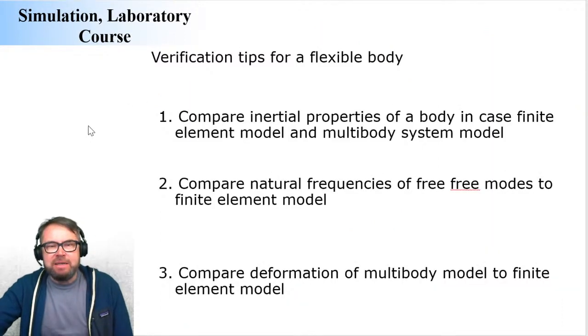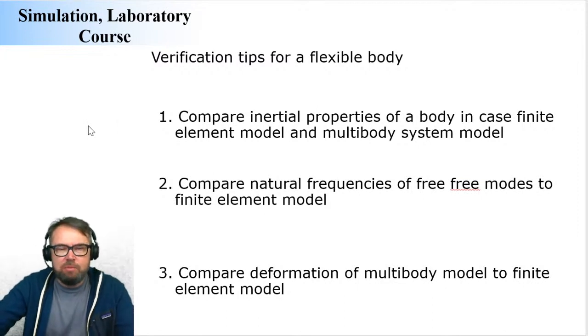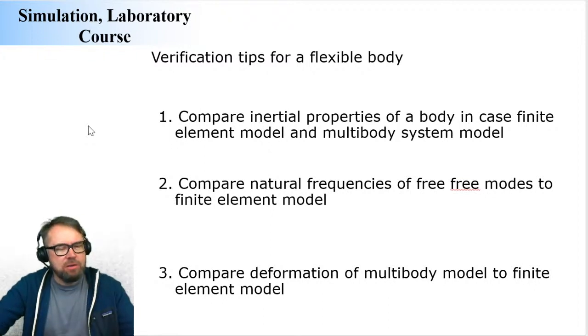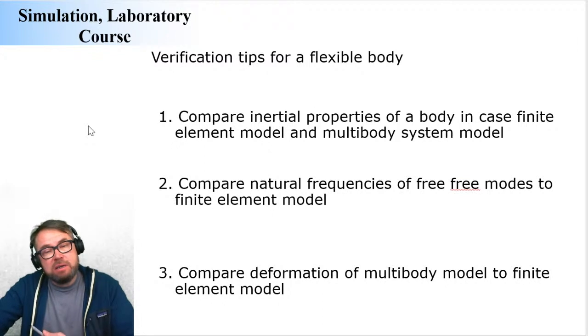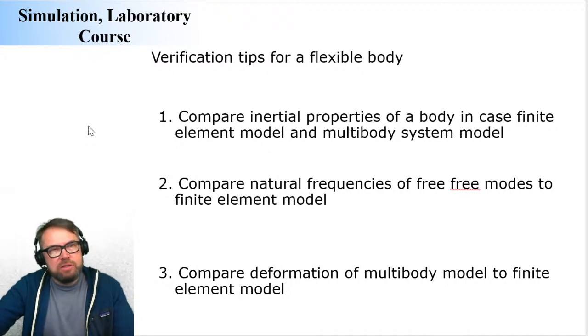Now, verification for flexible body. A very important thing is that when you're moving or converting information from finite element model to multi-body system dynamics, you can easily make mistakes about units. And one of the easy things to check is to make sure that you're checking your inertia properties. Just check how much the body weighs in your finite element model and in your multi-body system dynamics model.